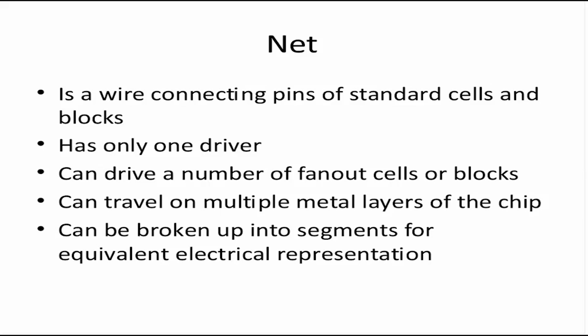So a net can travel on multiple metal layers of the chip, and it can be broken up into segments for equivalent electrical representation. We will see what segments are and how the STA tool uses those segments. This is just to clarify the concept of a net.